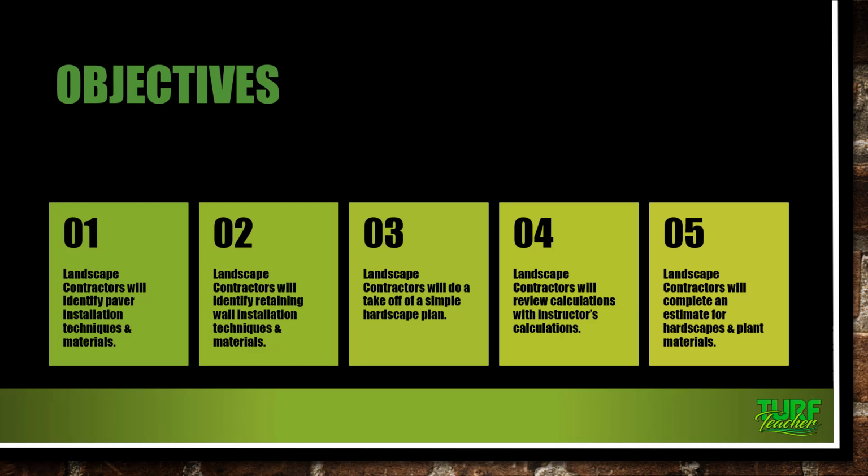Guys, when you are doing retaining walls for residential customers and they live in a neighborhood, make sure that you check their restrictive covenants or their bylaws, because they may or may not let the use of certain building materials in the neighborhood. We actually had to build a retaining wall here in Winston-Salem. I think at the highest point it was either 16 or 18 feet.